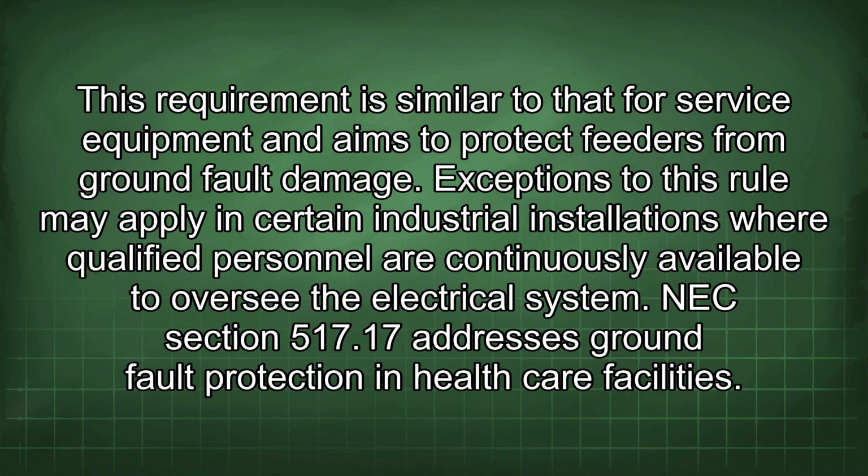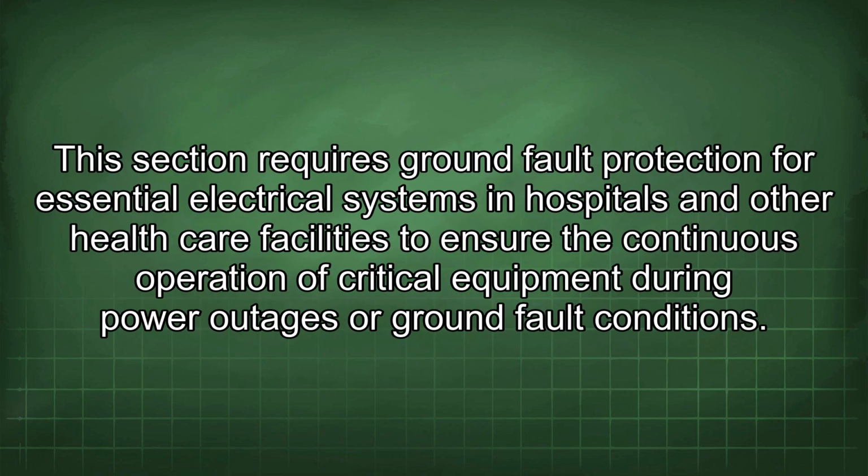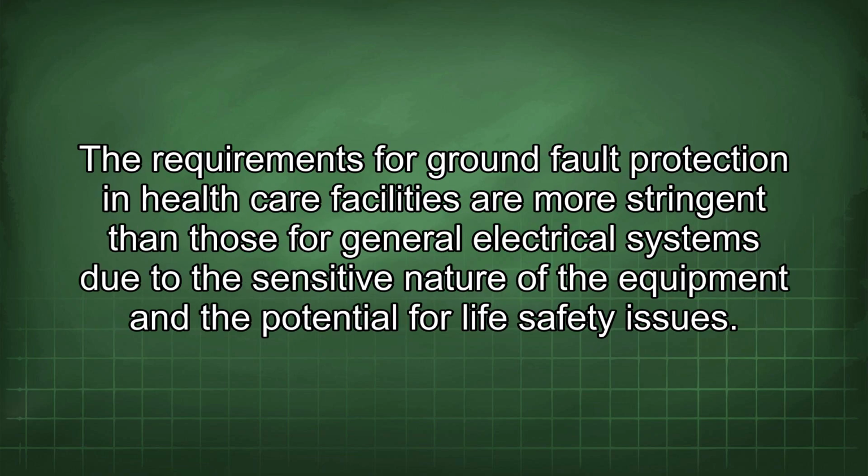NEC Section 517.17 addresses ground fault protection in healthcare facilities. This section requires ground fault protection for essential electrical systems in hospitals and other healthcare facilities to ensure the continuous operation of critical equipment during power outages or ground fault conditions. The requirements for ground fault protection in healthcare facilities are more stringent than those for general electrical systems due to the sensitive nature of the equipment and the potential for life safety issues.